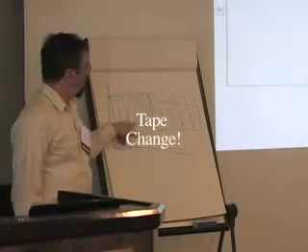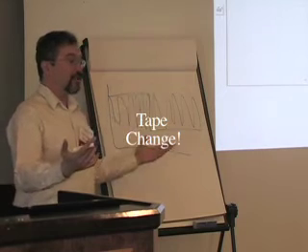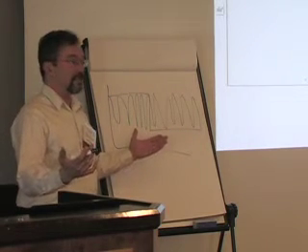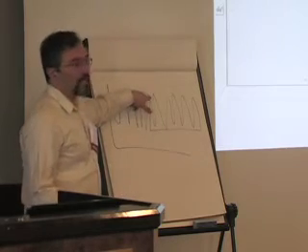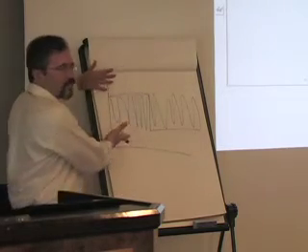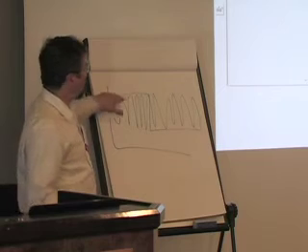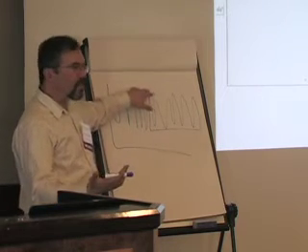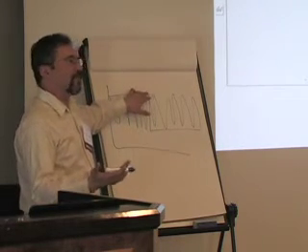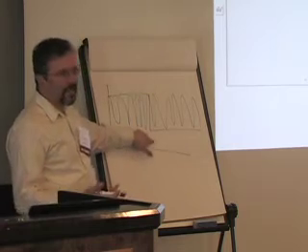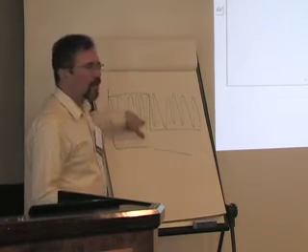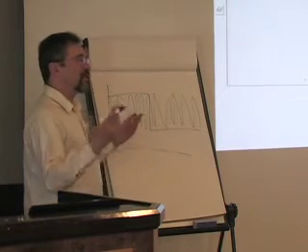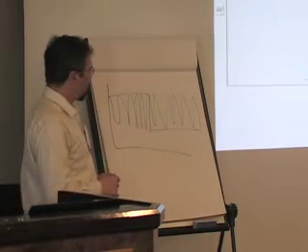They're not. But the implications for your storage requirements are radically different. This is sort of an extreme example, but this would have an autocorrelation of basically 1, almost perfect autocorrelation. There's just 1 hour of the year where it changes, and this would have a much lower autocorrelation. And you can see it obviously has a big impact on the storage requirement.